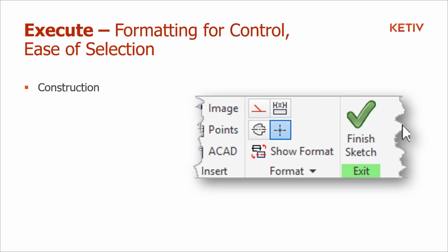And what that does is when you go to do this extrusion process or revolve process, a lot of times you have to pick 2, 3, 4, 5, 6, 7, 8 boundaries. Click, click, click, and make sure you exclude other ones. If you make some of the line work construction line work, it's going to make that easier. It'll exclude some of that information.